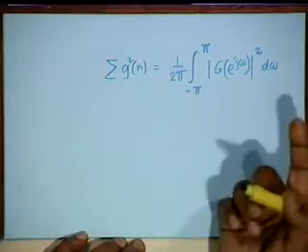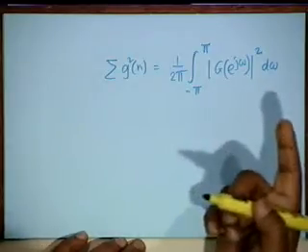It has to be. However, I must caution you that there are sequences for which Fourier transform exists, but Z transform does not, and vice versa. If the Fourier transform does not exist, then we cannot apply this theorem. However, we can apply the general modulation theorem in Z transform. Okay?